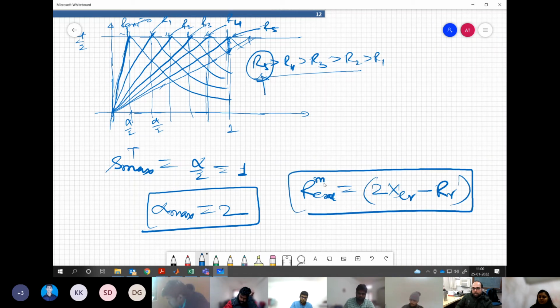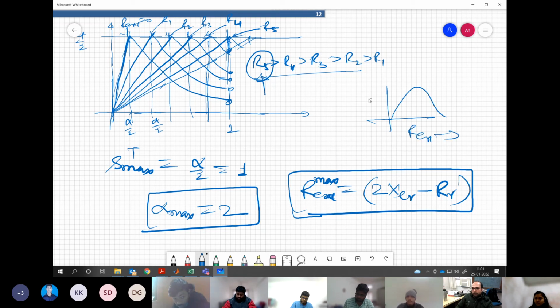This is the maximum value of resistance you can insert in the system for getting the most advantage. After that, this becomes disadvantageous. You are basically improving the starting torque with every insertion, right? So this does not keep increasing forever. There is a limit, it increases and then it falls down if you keep increasing the R external.